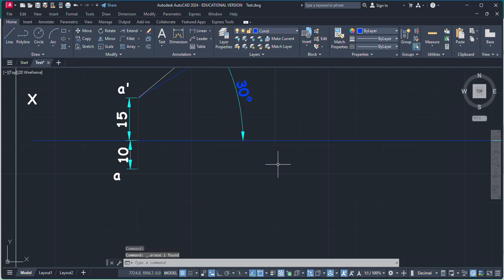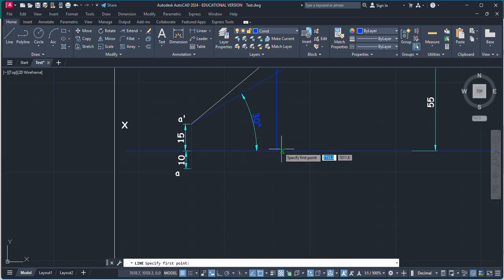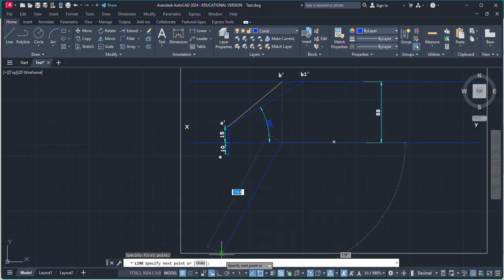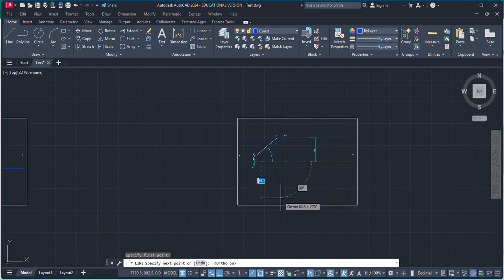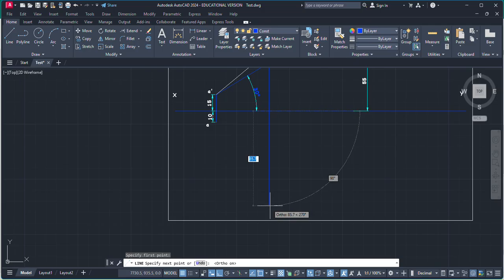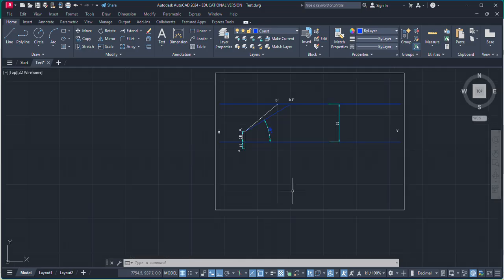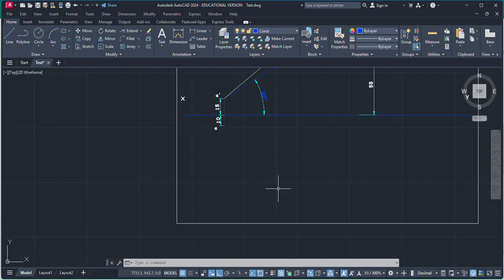remove this thing first. Now we know the horizontal distance between the end effectors is 50 mm. So just going to make this a little longer, and we know point B is somewhere on this vertical line for the top view. Now I need to find the end effector, which is point B. After finding this point B, if I connect it, this is the apparent line, and the point of the apparent line will lie on this line.